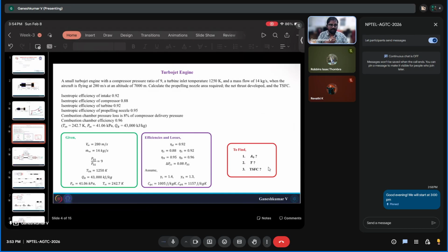So next week, we will do the same turbojet engine. We will keep everything the same, but the only thing is in week 4 you will be introduced to afterburners. In addition to the turbine, after the turbine you will also have an afterburner section where you will additionally add fuel and increase the heat, or the temperature, of the gases that are coming out. And that is going to affect your thrust and other things.